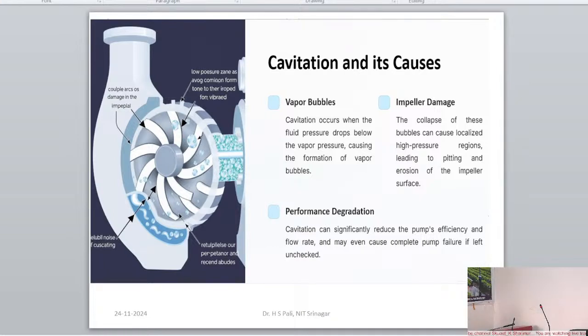So this is the part you can see here. The pump casing increases, and that will allow water to recirculate in this region. The impeller is smaller size here, the impeller is bigger diameter there. The efficiency is the ratio between the amount of energy going into the pump versus the amount of energy we get out of the pump. So ideally, we want this to be as close as possible to the peak for optimal performance.